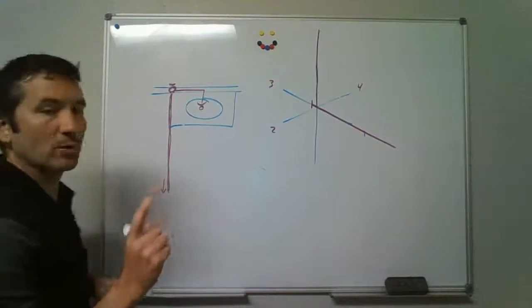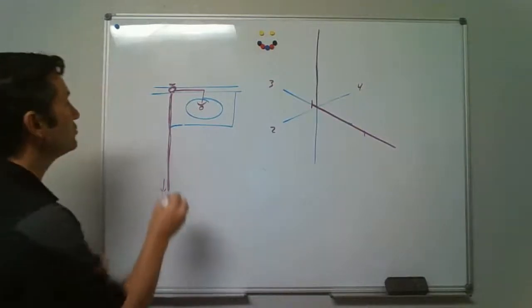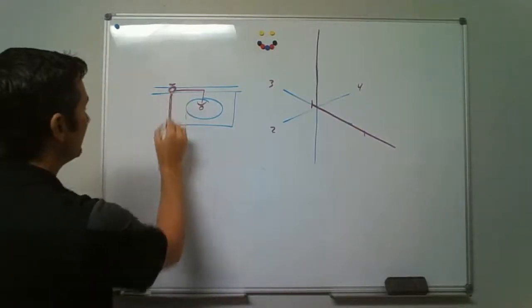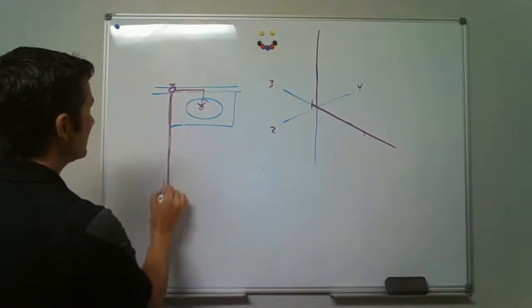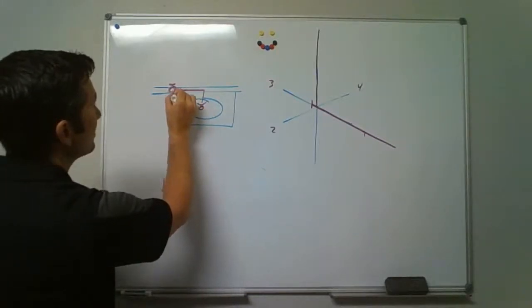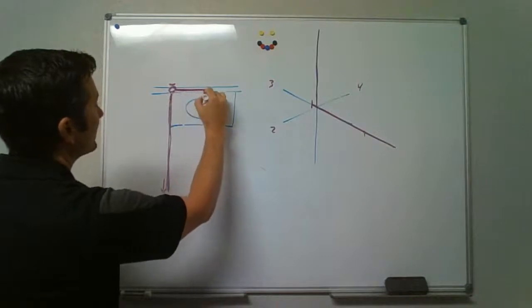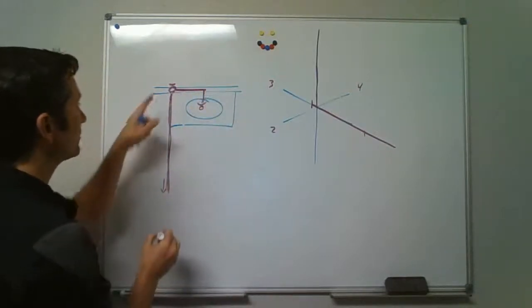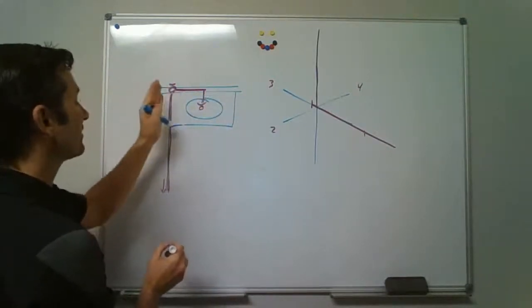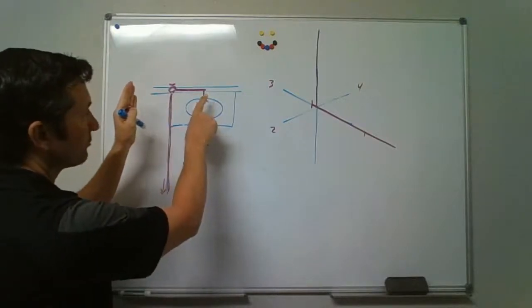Now, this is where it was getting a little bit trickier, as you just had to look as facing this. If you were standing on this line, this is arming over to the right for the lavatory. So this drain is to the left side of the lavatory, and you've got to arm through the wall to the right.